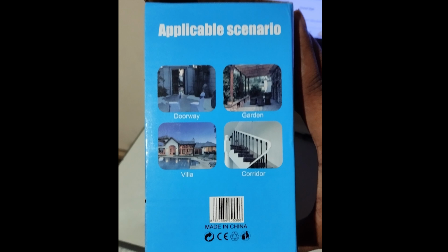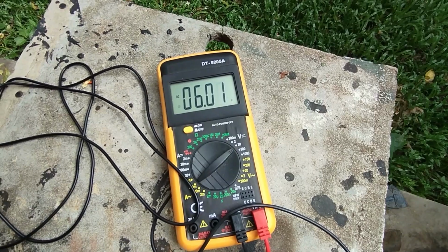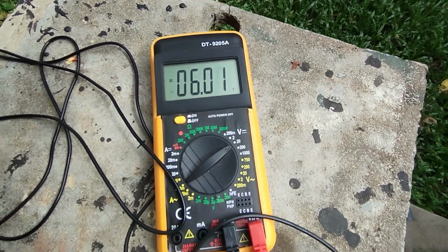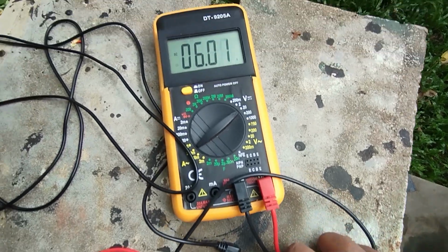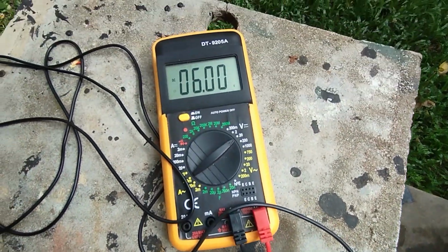This can actually be used anywhere you can easily access the solar panel, within the given cable distance. If you're planning to extend the solar panel cable, you need to consider energy loss, because in my testing the open circuit voltage of this solar panel reaches a maximum of 6 volts. There is definitely a voltage drop, sometimes even below 6 volts, and when connected to charging there is definitely a drop. That is pretty normal. Then you must have easy access to the solar panel.